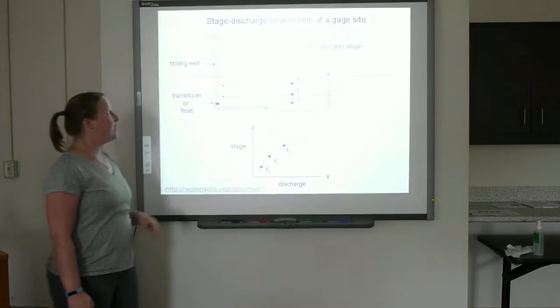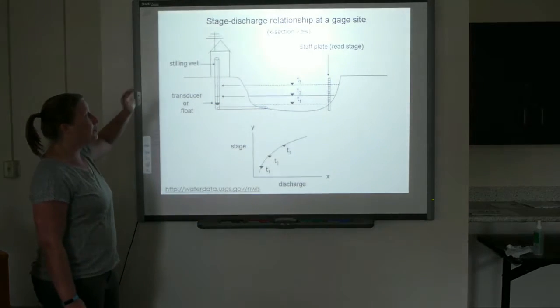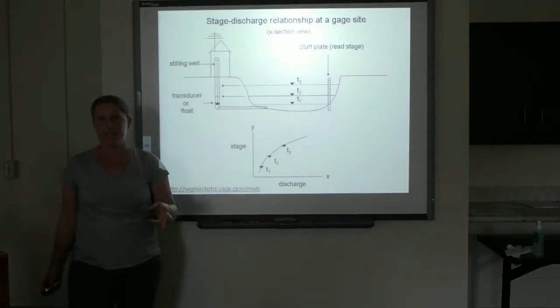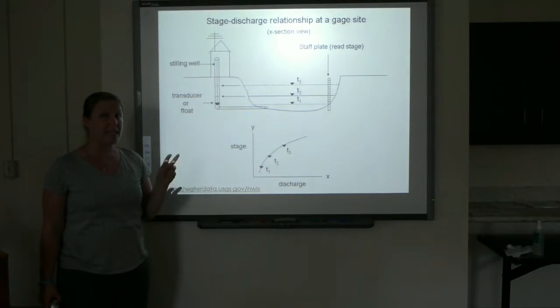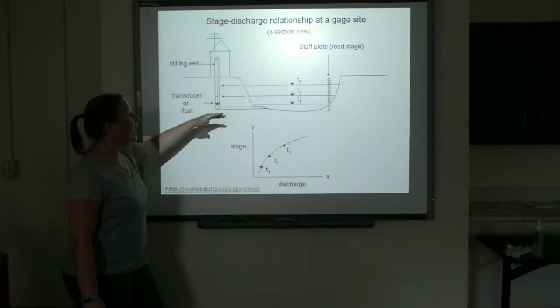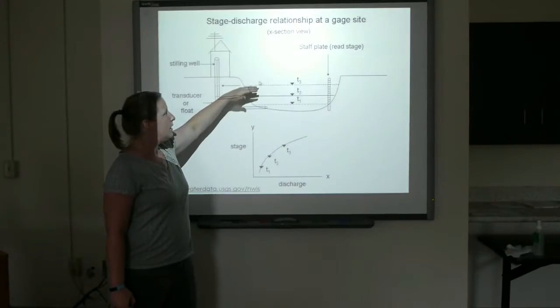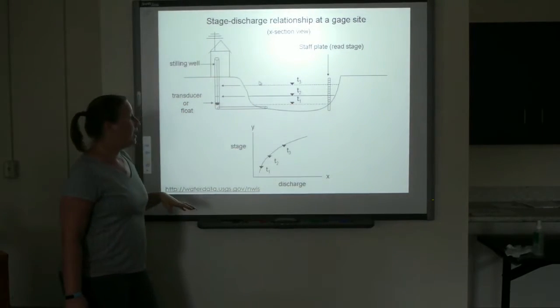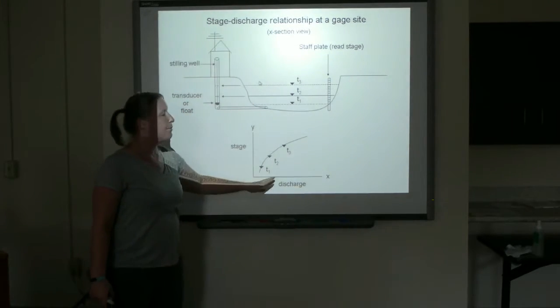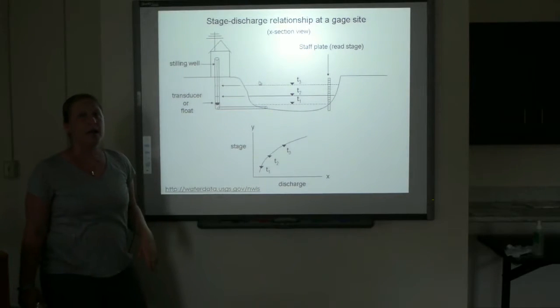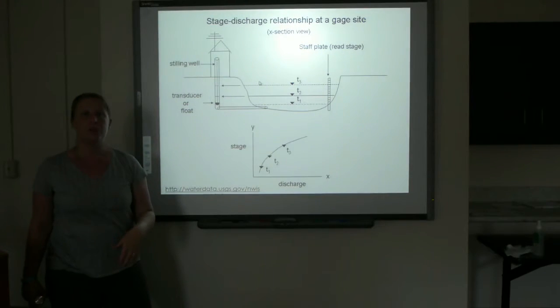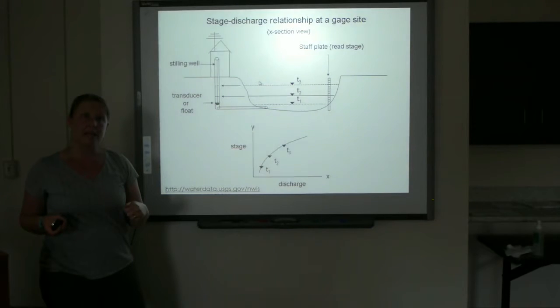The way that they do that is throughout a year they'll take at least 3 measurements at each site at different flow regimes, so at different depths of water. At different depths of water, they'll measure the discharge at that site. It used to be that they'd use those bridge cranes set up on a bridge.